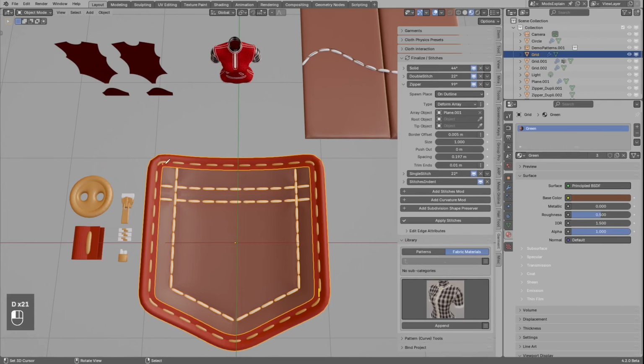Now, why this is not split into separate edges? Because there is this threshold angle which is quite high. If I reduce this threshold angle, you see we have now created split. The lower the threshold angle, the more the splits they are. So I just set this to high value, then it will generate round connected cyclic curve on the outline.